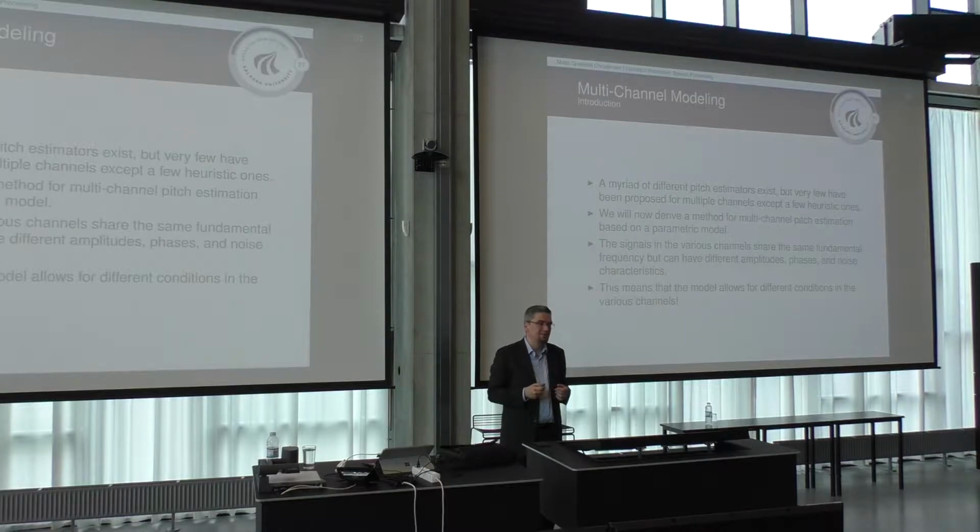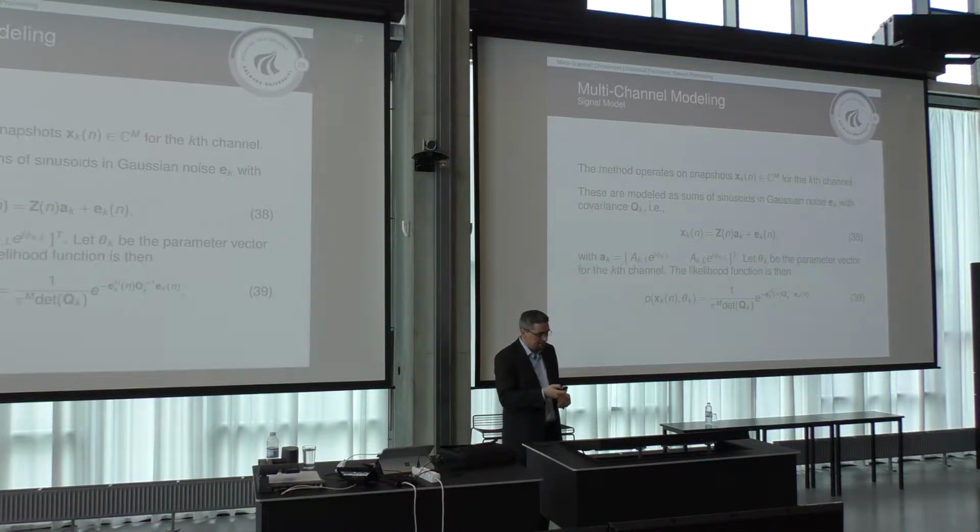We don't make any assumptions about certain array geometry or the noise power being the same in all the channels or the amplitude being the same in all the channels. So it means you can have different noise levels in different channels picked up by different microphones. You can have different microphone characteristics and all that. It doesn't matter. So this estimator here is quite general.